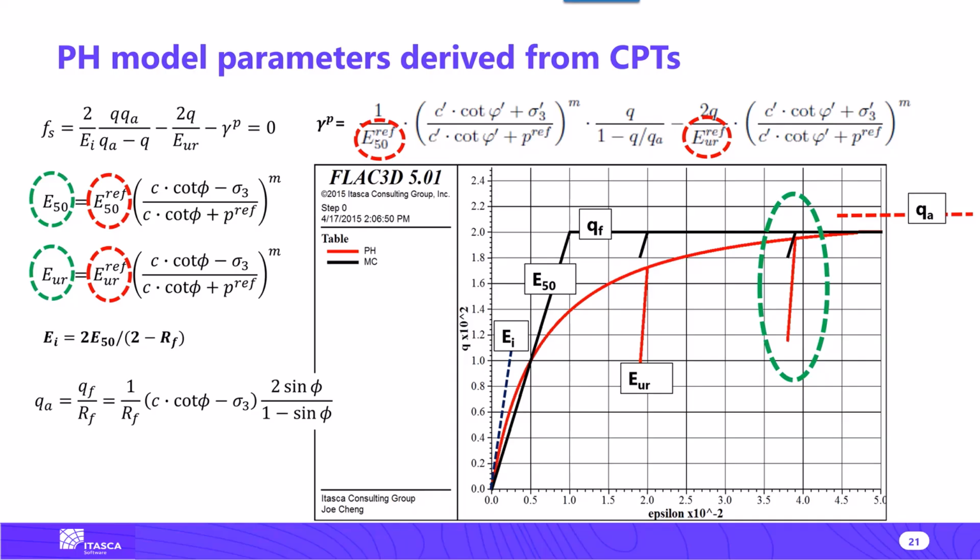First of all, the reference values that you see circled in red are not constitutive model properties. Those are just parameters. The way I do the calibration is to focus on the E50 and the Eur, unloading-reloading, and the E oedometer when it's pertinent, because those are the properties that we really need to estimate, and then reverse the formula to feed into the constitutive model the reference values.